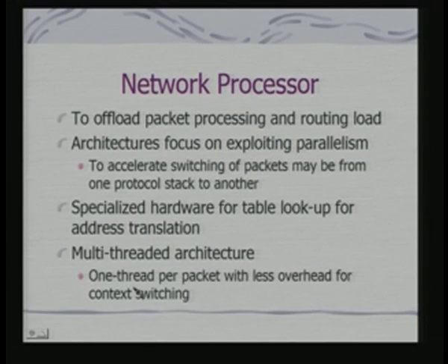Also, these are multi-threaded architectures. What is meant by multi-threaded architecture? It means that in the hardware itself there is support for individual threads. So, you can associate a thread with each packet, and the processor behaves in such a way that it handles a thread independent of other threads.